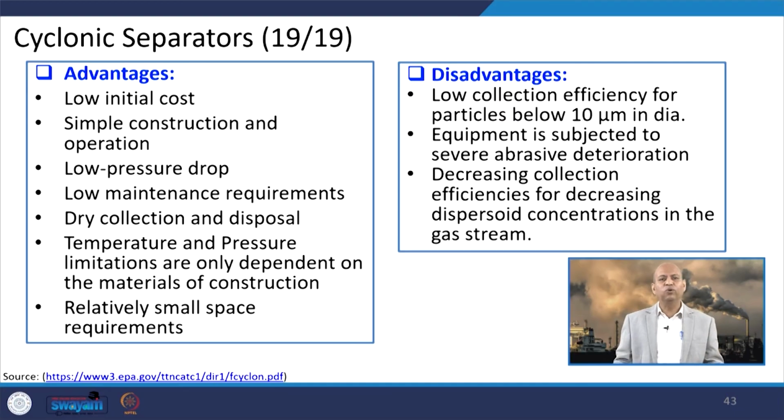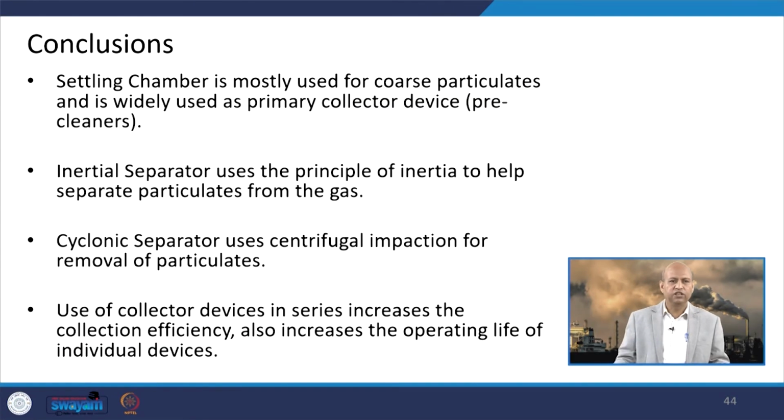Disadvantages are like low collection efficiency for particles below 10 micrometer in diameter. Equipment is subject to severe abrasive deterioration depending upon the particle size, its sharpness, etc. Then decreasing collection efficiency for decreasing dispersoid concentration in the gas stream. So, those are the disadvantages.